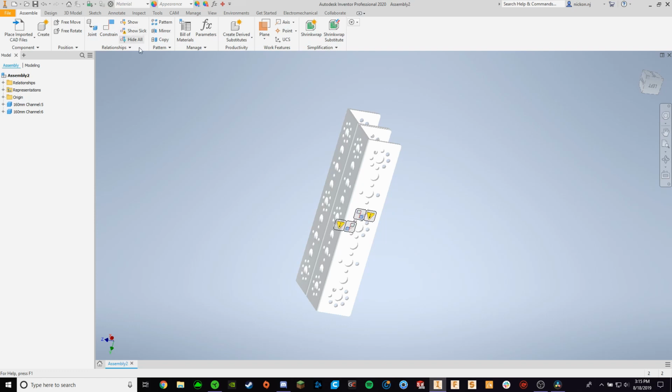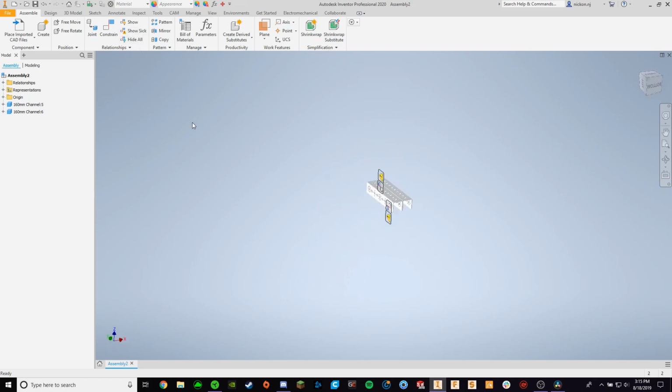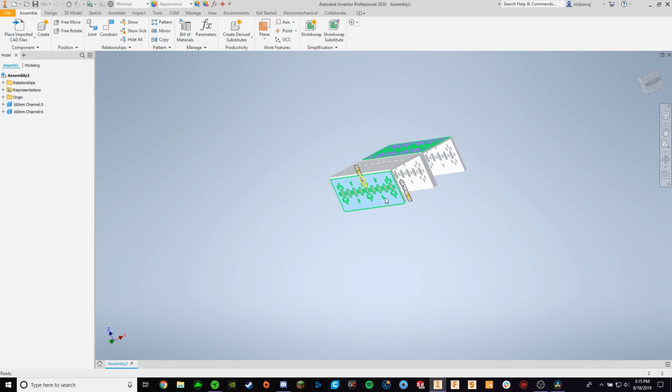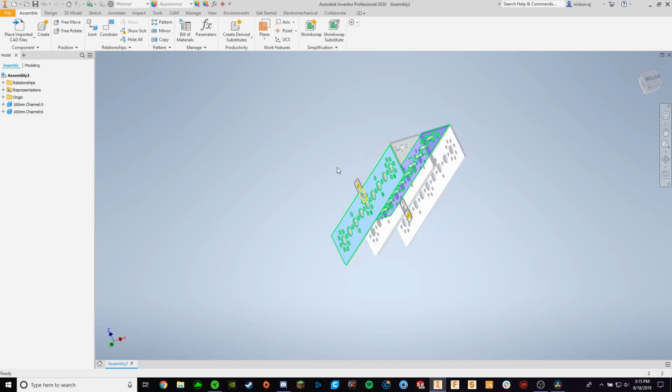This is going to reveal all of the constraints in your assembly that are impossible for Inventor to do, like all the problematic constraints, right? Here we can see that the problem is the stupid constraint that we told Inventor to make, which is obviously impossible. If we press delete on that, we can see now that things kind of go back to normal.